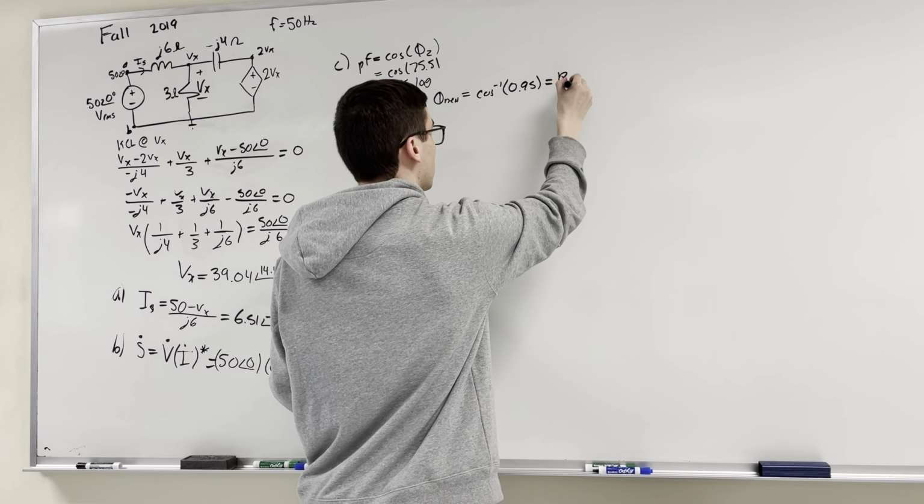So the capacitance C is going to equal, I'll write the whole equation now because it's important, the average power of the old, P old, times tangent theta old minus tangent theta new, all over 2 pi f, the frequency, times the magnitude of voltage RMS squared.